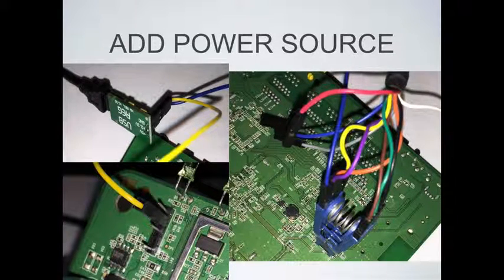It's just a USB power cable where you plug it into the USB, and it can supply you 3.3 volts or 5 volts. Then you take that power and attach it to the VCC of the chip, replacing the red cable.